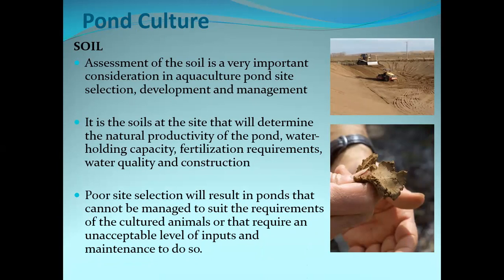So you really don't want to utilize or select a site where, let me say for instance, the soil is not very clay, right? And it's more sandy and it's not retaining water well, right? So you might have frequent, the water will drain out a lot faster. You might have to do a little more work with respect to trying to compact the floor. So you want to kind of avoid setting a system in place where you have to do frequent maintenance more than necessary. Okay?